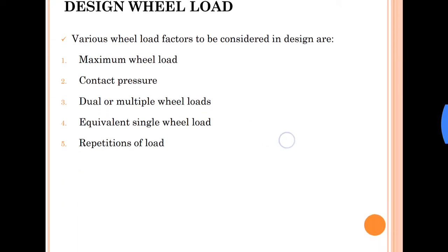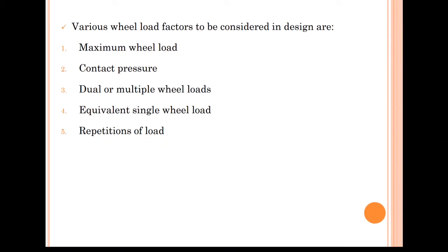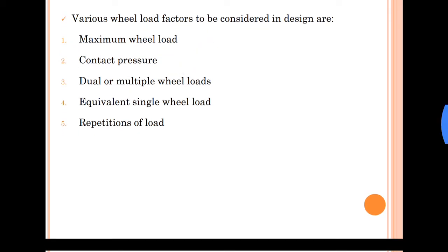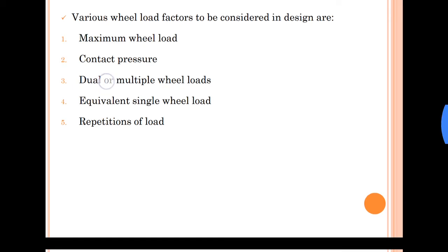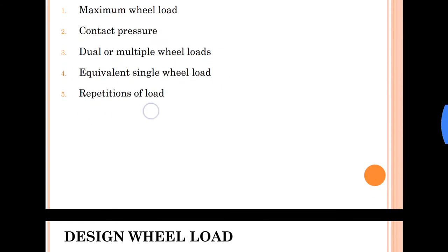Now under design wheel loads, we need to consider a few factors. Various wheel load factors to be considered in design are maximum wheel load, contact pressure, dual or multiple wheel loads, equivalent single wheel load, and repetition of loads.